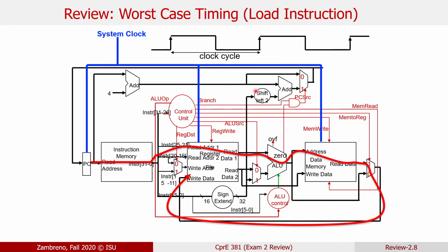So the branch instruction in its immediate field is encoding a PC offset. It's a number of words away, a number of 4-byte quantities away from our current PC plus 4 value. So in order to turn that into a byte offset, because that's ultimately what our program counter is supporting, we basically do a shift left 2, concatenating 2 zeros at the least significant bits. We're getting a savings in terms of the encoding of the instruction that way. In that 16-bit field, now we're basically allowing for 18 bits of byte offset from our program counter. It lets us branch that much further away.